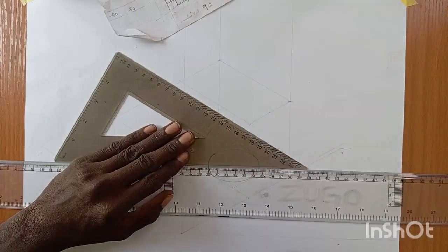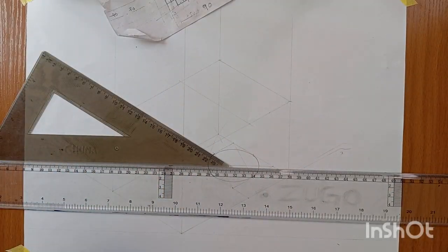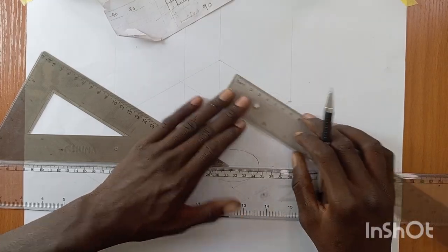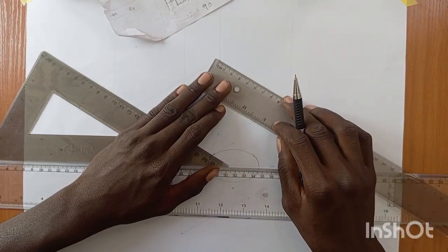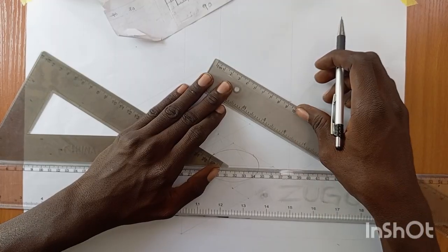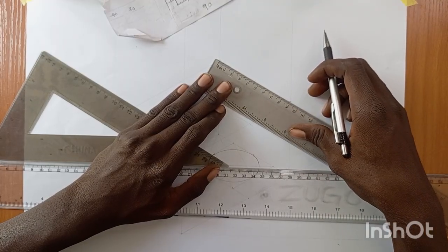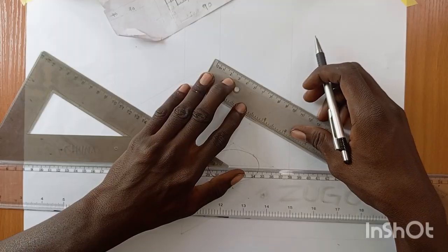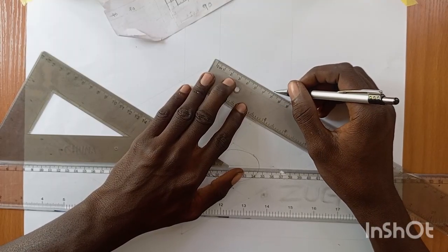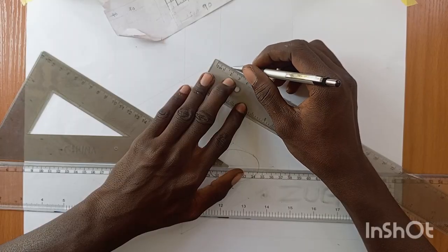Take this line. And the next thing is to divide this line into 2. It's given us 90. 90 by 2 is 45. And you measure 45 from one side. In that 45, you are going to take 25 upward and 25 downward. To do this in an easier way than striking it, you just take your 25 up and down. You will take here 5, 10, 15, 20, 25. And then of course here we have 5, 10, 15, 20, 25.